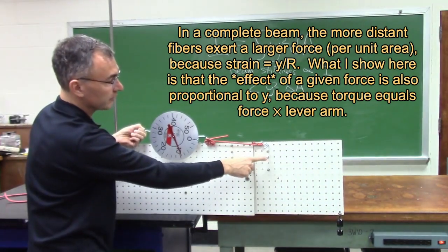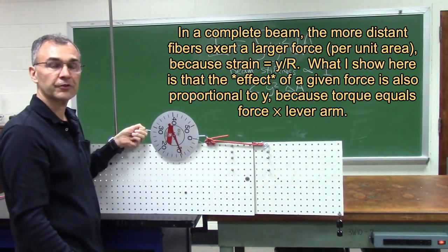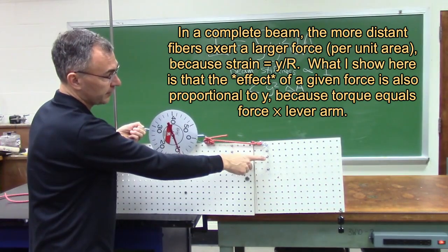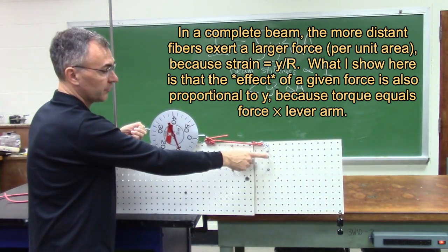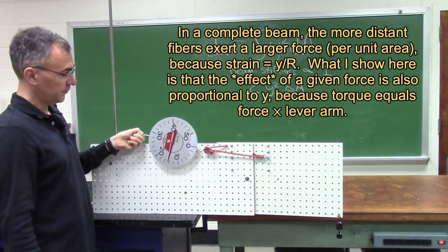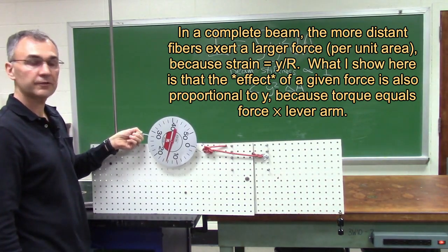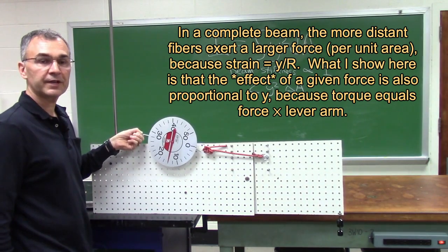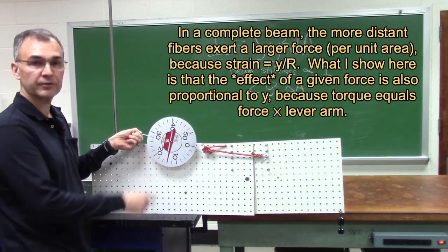Let's go down to a lever arm of 3.5 and see what that corresponding force looks like. I predict it should be bigger by a factor of 5.5 to 3.5 because I'll need a bigger force at this smaller lever arm to produce the same torque. So now we have a force of about 15 newtons, which actually makes sense because the ratio of 5.5 to 3.5 is about 1.6, so we'd expect about 15 or 16 newtons.